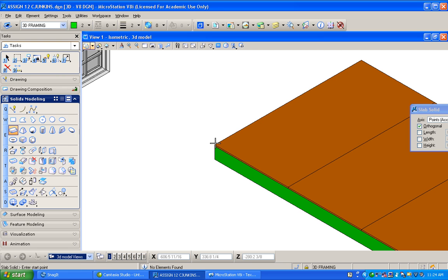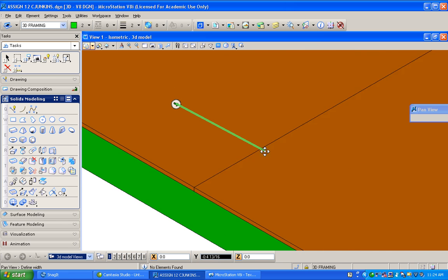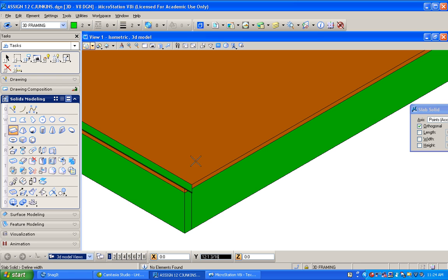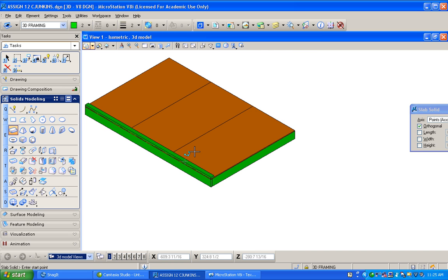And we're going to lay down a 2x4. Remember, we talked about using 2x4 floors, so it's going to be colon 1.5 tall. Bring it all the way to the other end. We're going to snap it. Lost my mouse. And colon 3.5 for the height. So we have a single sole plate.